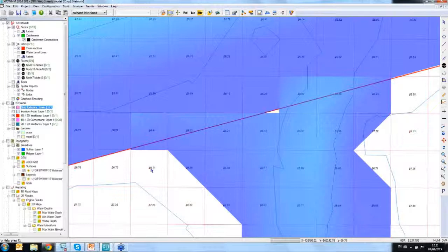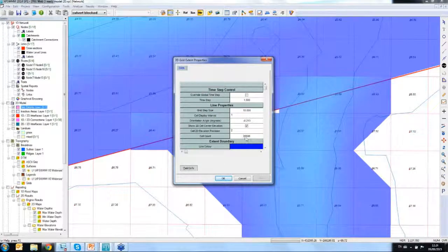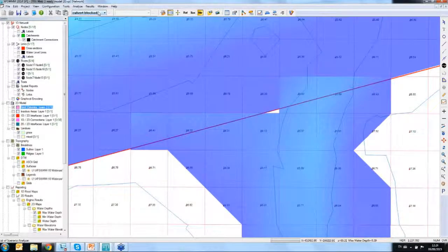Everyone's been really impressed with the speed at which the analysis took place with the 1D. It was really quite quick. With the 1D, 2D, how long would it take for that kind of model to run the analysis typically? Okay, so in this model, I did have 3 different scenarios, and grid size was 10 by 10, and we did have, let's say, 7,000 cells. I think one scenario did run about 15 minutes, but obviously it depends on your time step as well.